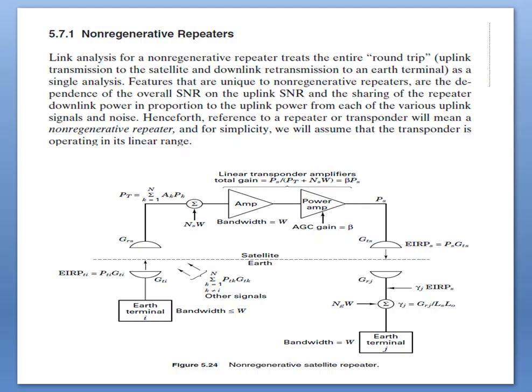A satellite transponder is limited in transmission capacity by its downlink power, the earth terminal uplink power, satellite and earth terminal noise, and channel bandwidth. One of these usually is the dominant performance constraint. Most often the downlink power or the channel bandwidth proves to be the major system limitation. Here the figure explains the important link parameters of a linear satellite repeater channel.